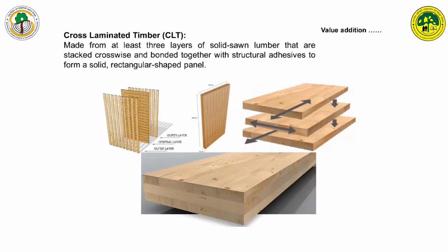And in recent years, plantation timbers can also be utilized by making cross-laminated timber. Here it is just like plywood, however in plywood we always go for veneering. We take a thin sheet of wood, maybe the thickness can go up to 1.5 to 2 millimeters. But in the case of CLT, we don't need a peeling lathe. Thicker material ranging from 1 centimeter even to 1 inch can be utilized, and they can be placed in the same way as veneers in alternate layers, like plywood, and it can be bonded with cold setting resins, because as the thickness is more, we cannot apply hot pressing here.